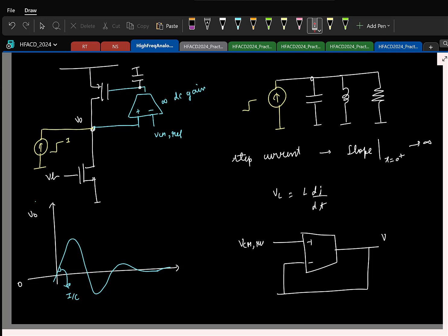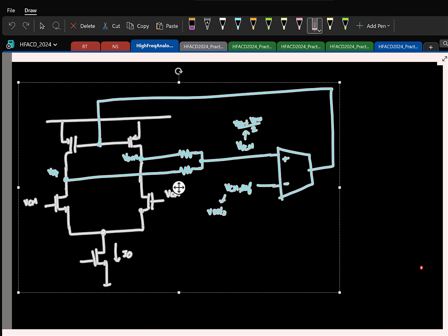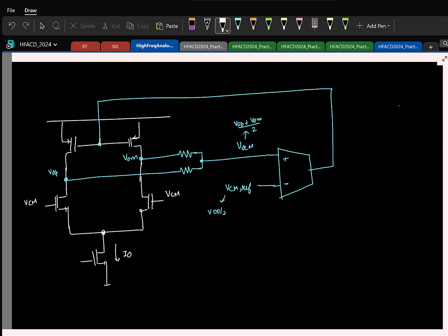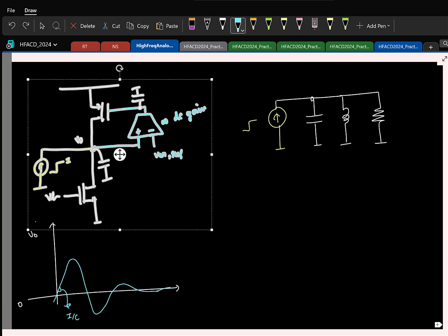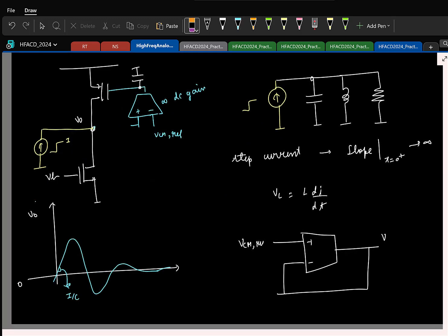And actually something I missed here, so hold on. In the circuit common mode feedback, remember we also have to compensate it, and we did compensation using a Miller capacitor like this. So I'll also include that. You'll have the capacitor like this, and a resistor here, I missed it, I'm really sorry.